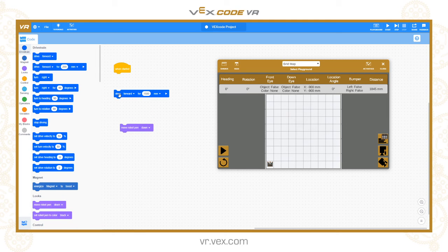So in this case, if I do this, the robot is leaving a line behind it, because this non-blocking command was issued, and then this one was issued, and of course we never tell the robot to stop, so it doesn't. But you can see the difference between a blocking and a non-blocking command.